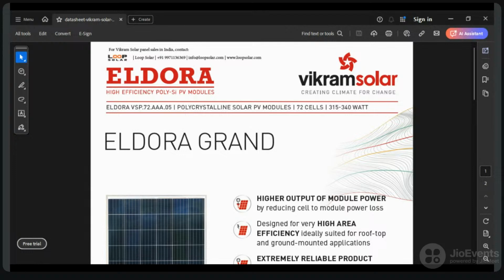So I took both the monthly requirement and the bi-monthly requirement. Suppose the rate is 3 rupees. Then the monthly cost will be 180 into 3, we'll get 325 rupees, and bi-monthly it will be 651. PV generation per day units will be 3.83, and bi-monthly generation will be 230 units.